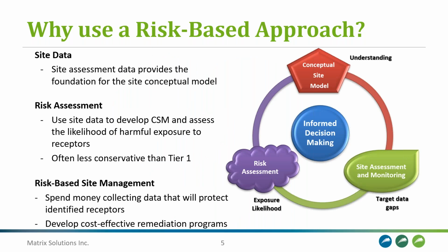So the foundation of risk assessment is the conceptual site model. It's built based on available site-specific and regional publicly available information to develop a preliminary understanding of the risk to receptors for a given site. Once we develop the conceptual site model, we typically use numerical modeling to test it, which serves to build confidence in our understanding of the site, predict future contaminant migration, evaluate remedial options if needed to protect receptors, and provide an assessment of confidence in the proposed remedial approach. So this risk-based workflow leads to informed decision-making for a given site and helps support monitoring or data collection plans that enable us to refine the conceptual site model.